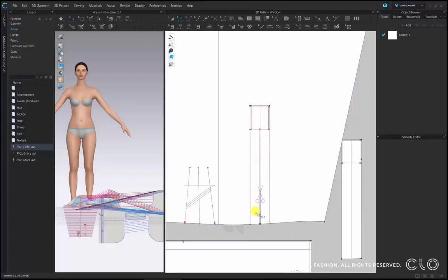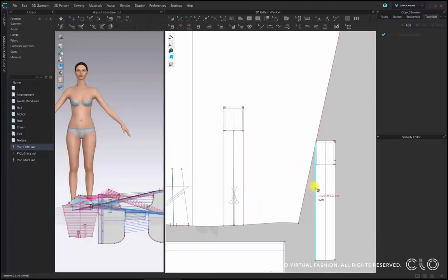Now I will try to sew the overlapping placket in here. I will do so by changing to the segment sewing tool. First I will sew the placket from the outline. Just connect the notch to the sewing line so that the shape is exactly the same.